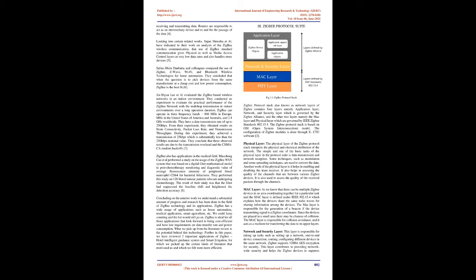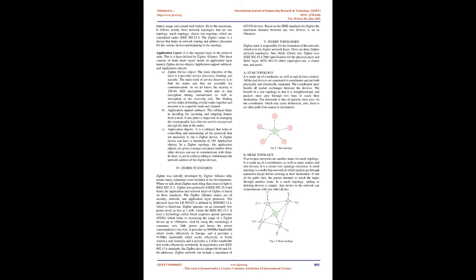MAC layer. As we know that there can be multiple Zigbee devices in an area coordinating together for a particular task, and the MAC layer is defined under IEEE 802.15.4, which explains how the devices share the same radio waves for sharing information among the devices.